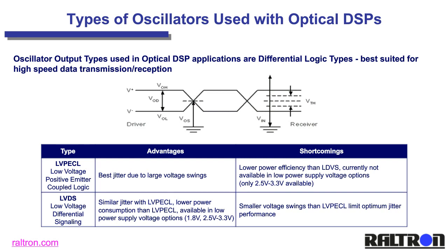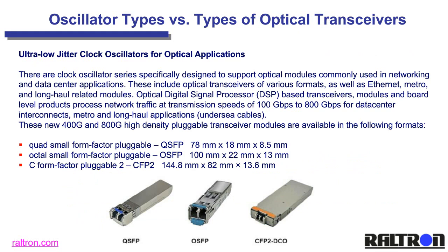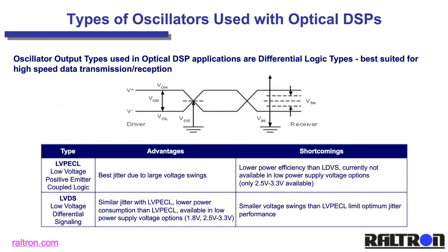Well, if I may, Sasha, can I actually ask you about the difference between the LV-PECL and LVDS? You had said something along the lines of nowadays the LVDS is closer in jitter performance to the LV-PECL. Does that mean that they are comparable, is LVDS catching up? Is one more prominent than the other? Would you expect LVDS to evolve to be more comparable to the LV-PECL when you're comparing those in that trade-off that you were talking about for engineers? Or is that always going to be the two?